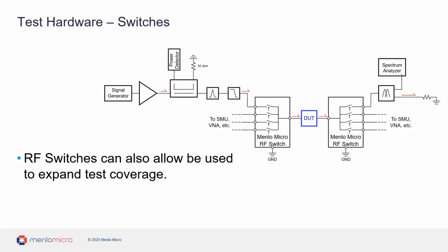In this case, choosing a MEMS switch is critical. Traditional RF semiconductor switches are unable to pass both DC and RF signals. Some specialized and expensive mechanical relays can, but even these will have a larger impact to high-frequency RF performance than a MEMS switch, in addition to the longer switching time and reliability concerns that we discussed previously.